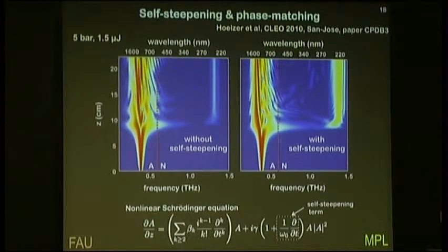So what we're seeing is that the fiber is allowing the pulse to become temporarily focused to a very short pulse, very nicely. Self-phase modulation in combination with weak anomalous dispersion does that for you. Then we have this self-steepening term becoming very important. We have phase matching to resonant radiation in the ultraviolet. The ultraviolet light gets generated, and once it's generated, it just continues to propagate in the fiber.